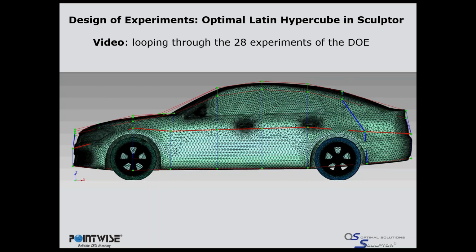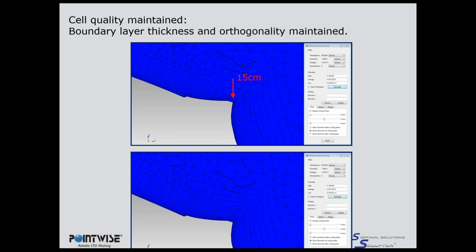So this populates our design space in 4 dimensions. And it creates these instantly, and then we can export all of these designs and send them to the OpenFOAM solver, and that can be on your local machine, or they can be sent out to a cloud or some high-performance cluster, and then we get the information back from that.